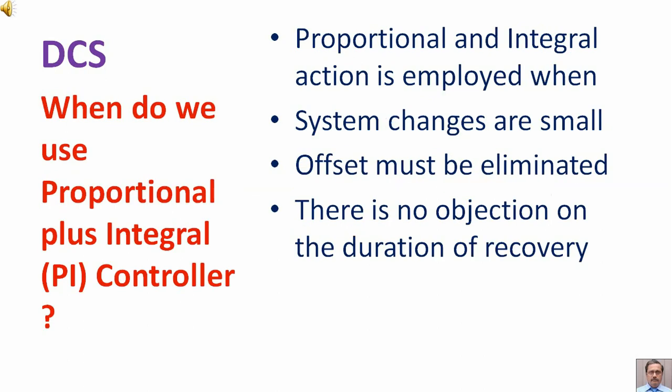When do we use a proportional plus integral controller? Proportional and integral action is employed when system changes are small, offset must be eliminated, and there is no objection to the duration of recovery.